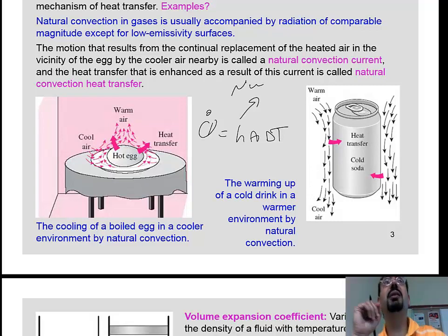But that Nusselt number, this time, remember last time we had Nusselt number as a function of Reynolds, because that's what's moving the fluid. But here, there is no Reynolds number. It's not moving the fluid. It's not the V. It will be some other dimensionless number that will result in this movement. And that dimensionless number is basically related to the buoyancy. The fact that you get hot, you get lighter, you move up. Right?